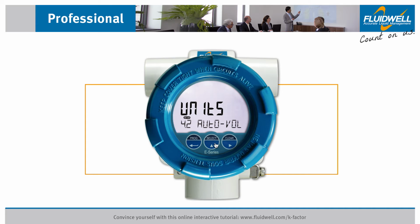Press Prog to change this setting. We are going to select the Hand mode, as we manually want to set 2 different K-factors. Press Prog to store this setting. Use Clear or Select to navigate to Menu 1 Total. In this menu, you can set the display settings and K-factor for total.